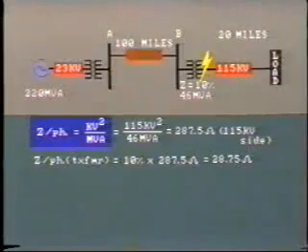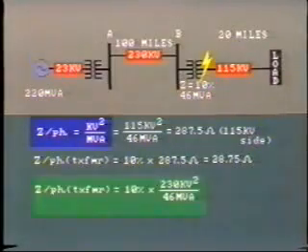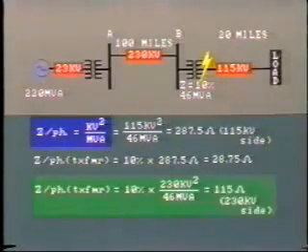But wait a minute, we may just as well have inserted the 230 kilovolt value for the transformer voltage instead of 115 kV. In this case, the ohmic impedance would come out to 230 kV squared divided by 46 MVA times 10%, equals 115 ohms.